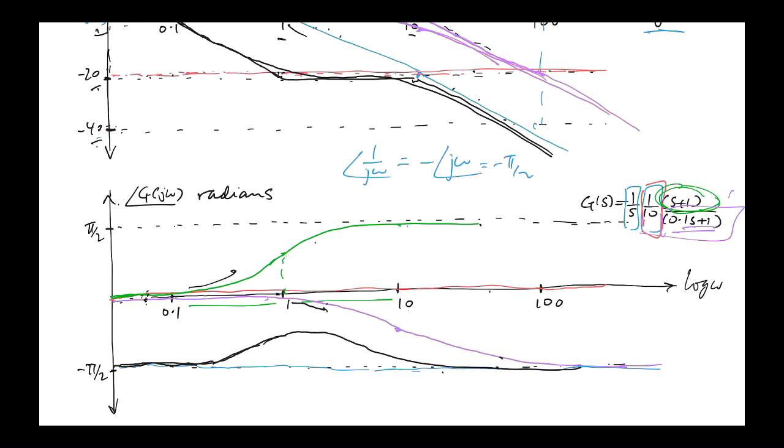Okay, it's very useful to be able to just by hand know how the Bode plot is going to change when we add poles and zeros to transfer functions, because that's often what we do in control design. We start off with the model of the plant, and then we add poles and zeros to it by multiplying the plant transfer function by a controller transfer function before closing the loop. Okay, and so knowing how the product of the plant and controller transfer function will change as we add poles and zeros to it in terms of how the Bode plot changes is a useful thing, as we'll see later on.